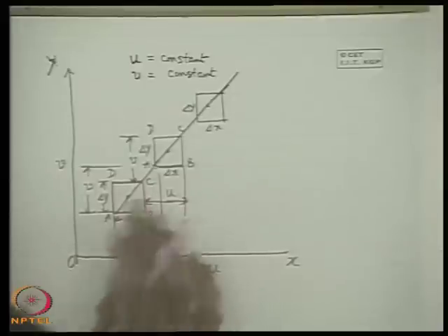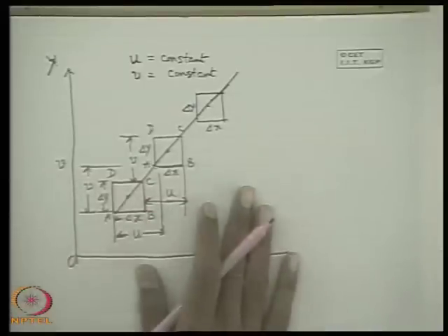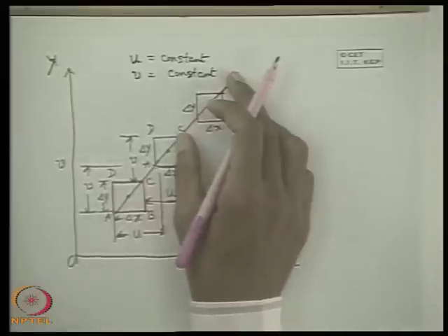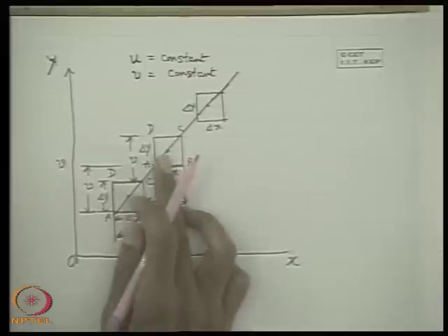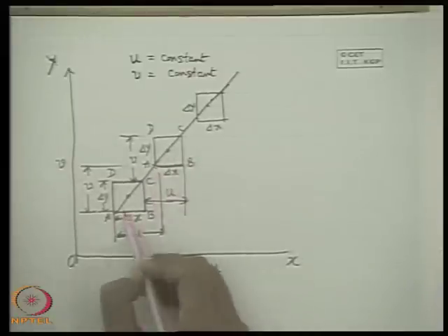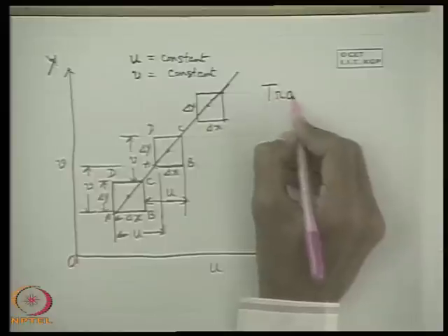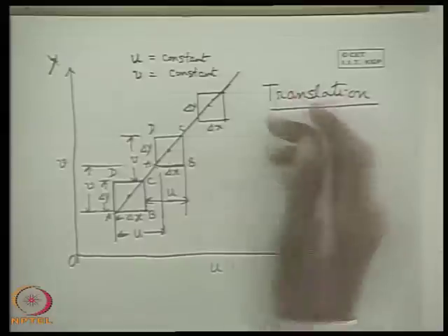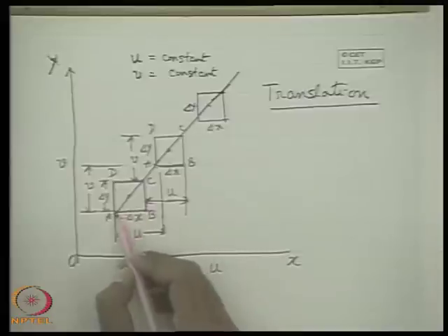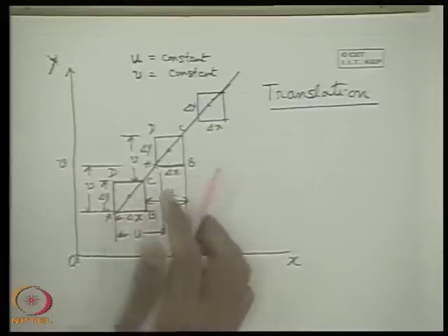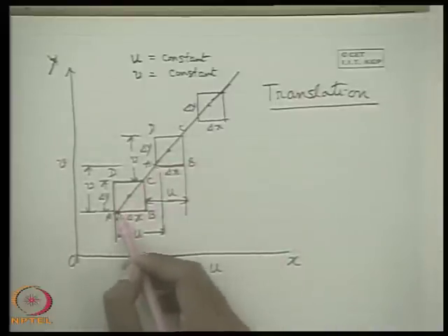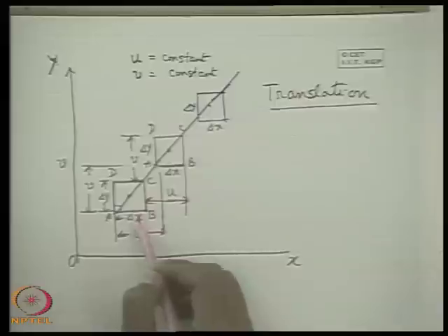That means each and every point moves with the same velocity and their displacements are the same, so that the sides are not changed in course of motion, and also all the sides move parallelly. That means AB comes here parallel, AD and BC are parallel. This is simply known as translation. This happens in case of a solid body. If a solid body is given a rectilinear motion, the solid body displaces like that. None of its sides are altered, and the sides are translated parallelly. The displacement takes place so that the included angle between two linear segments remains unaltered.